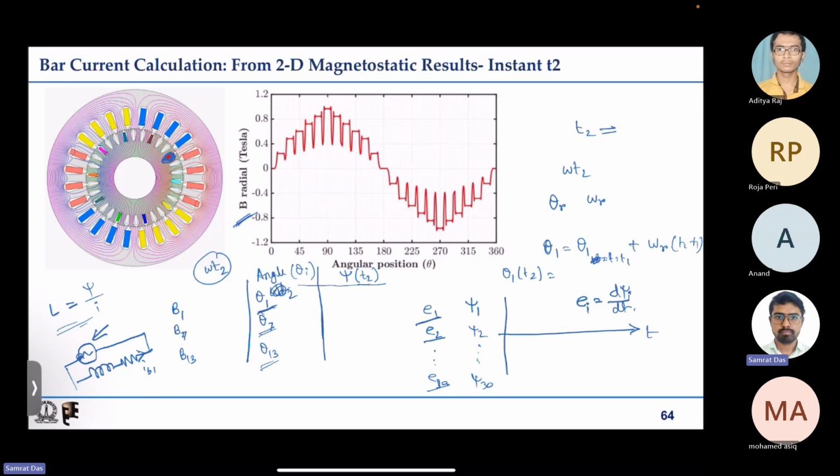So actually, what happens is it is the resultant flux. Both excitations are there, and the air gap flux density is the resultant flux density, right? But for this analysis, we have to first know what current is getting injected in order to calculate the flux linkages of the rotor bars. So this is the first assumption that goes into this type of analysis.